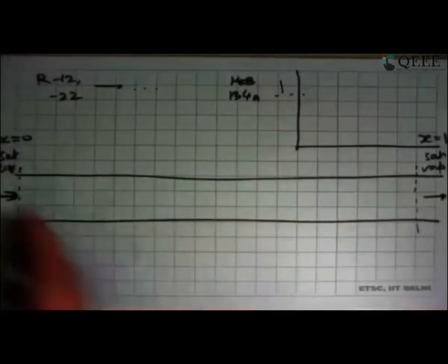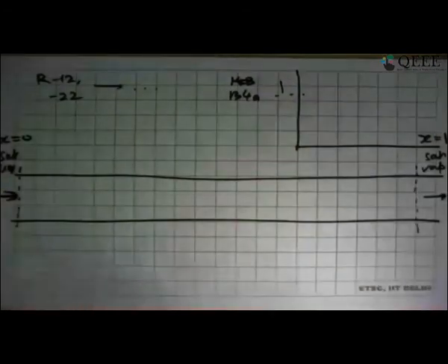So let's see what happens in this. And this is very different from what we have looked at in pool boiling, in that this is now forced convection, internal boiling. Much the same will also happen in natural convection, internal boiling, which is that power plant boiler tubes that I was showing you about. So let's see what will happen here.